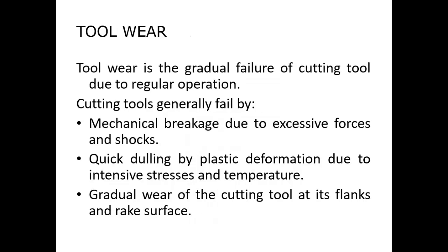Generally, why do cutting tools fail? Either by mechanical breakage due to excessive force and shocks. If I apply a large amount of force to cut the workpiece, obviously the cutting tool will fail. Second, quick dulling or plastic deformation due to intensive stress and temperature. If I perform machining operations at the highest temperature, then obviously the cutting tool will melt itself. Plastic deformation will happen. And the last one, gradual wear of a cutting tool at its flank and rake surfaces.